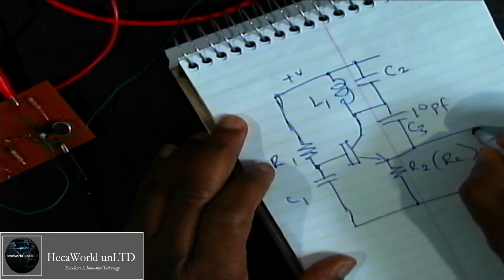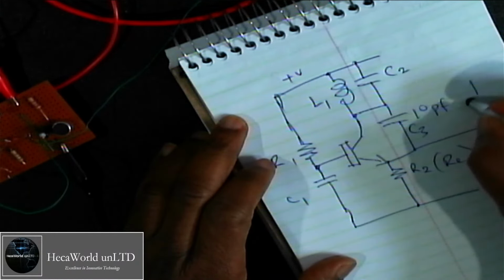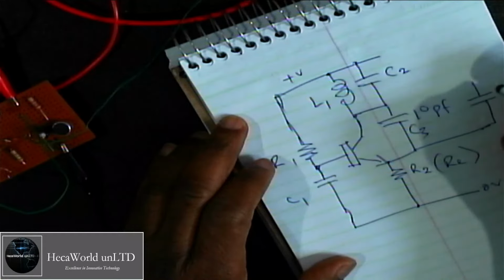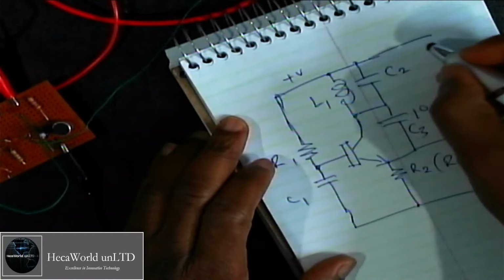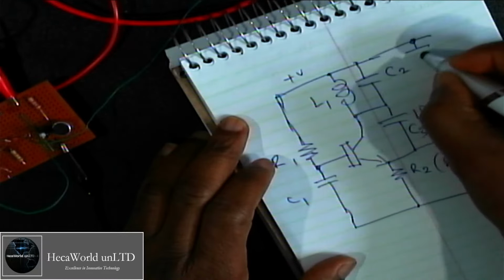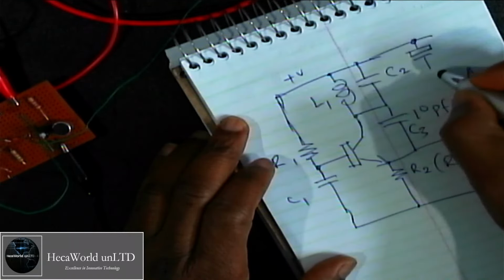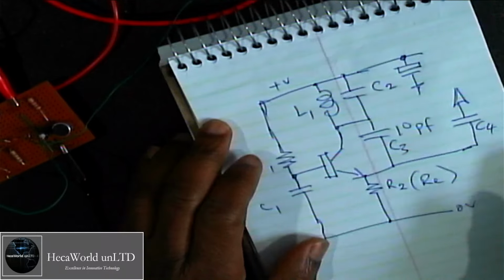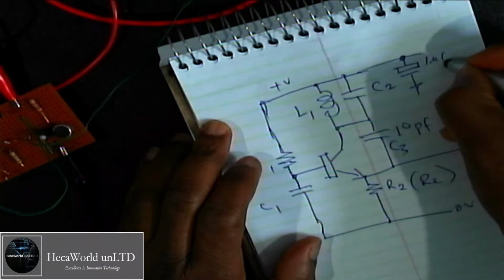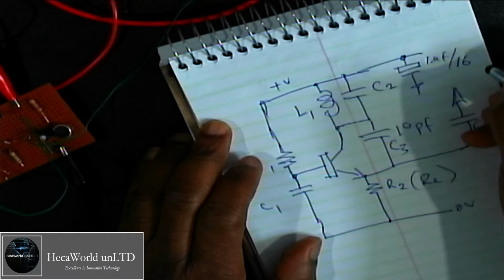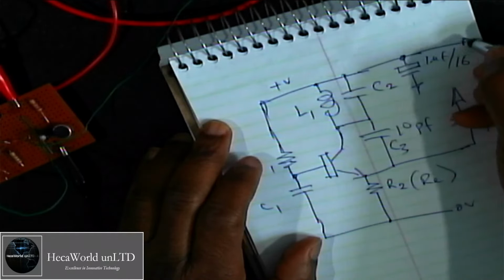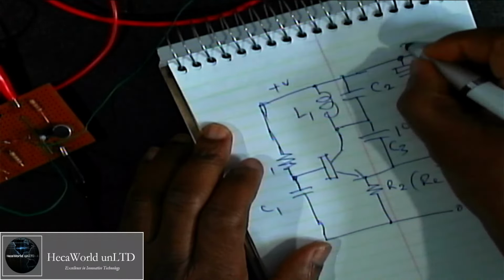We're going to take our antenna from the emitter circuit. We're going to call it C4. So then remember, for the power supply, you need a filtering network here. We're going to use a capacitor, 1 microfarad, at let's say 16 volts or more. Our power supply is in this case about 3 volts.